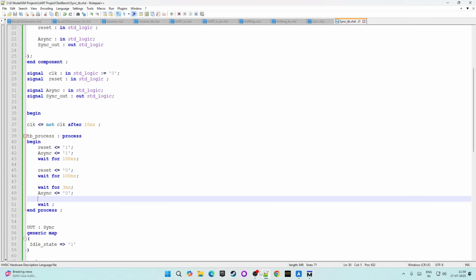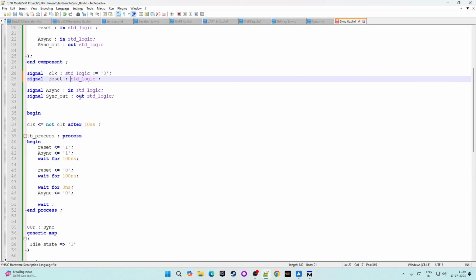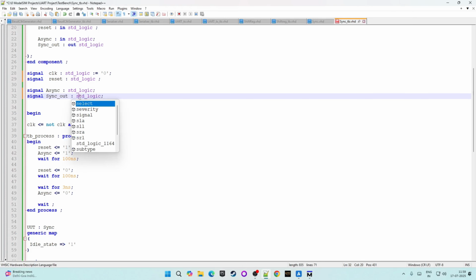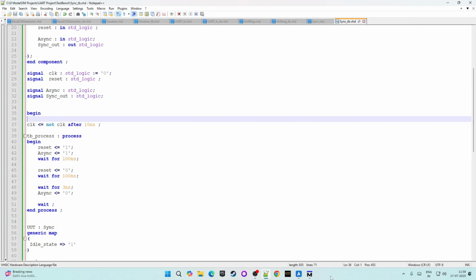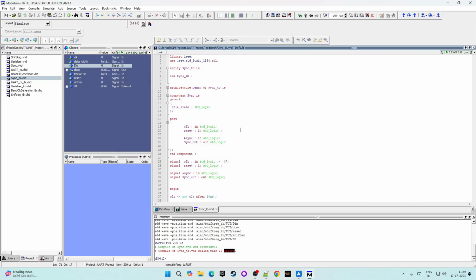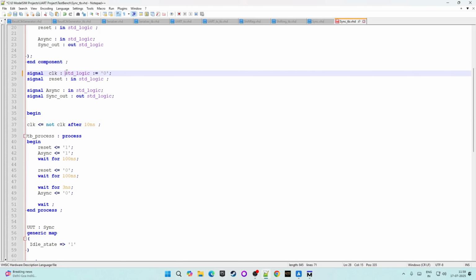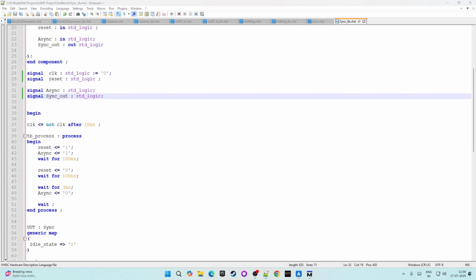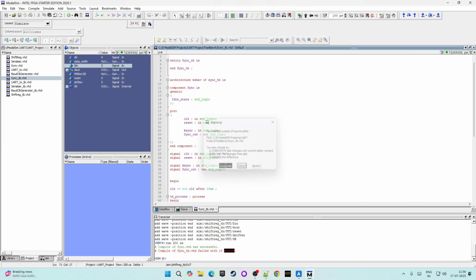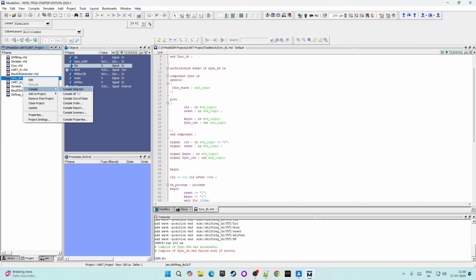Okay. So we have this signal declaration and we have not removed the direction from this port section. So let's see how it looks now. Save this. Now close this. Okay, overwrite. Seems like it's not updated. Okay, let's remove this once again. Now save this. Now go to this ModelSim simulation and overwrite. Okay, now compile, compile selected.